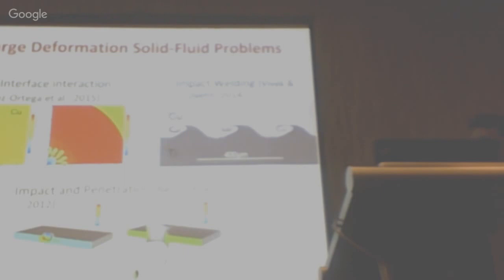So here are some examples of large deformation elastic plastic flow in solids. Here is a pressurized gas contained in a cylindrical cavity made up of copper. So this is a solid, and there is a gas inside. A converging shock is set up in the solid. The shock passes through the interface, bounces off the axis of symmetry, and then there is a reshock where it passes through the interface again, which gives rise to these nice finger-like structures in the solid gas problem here.